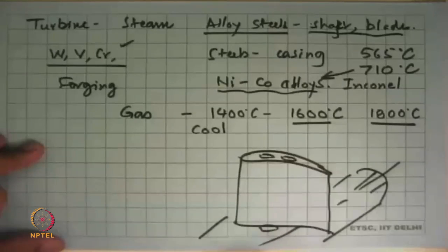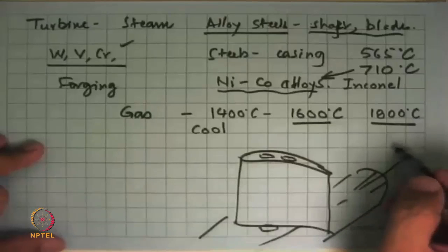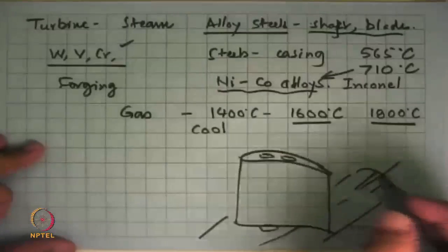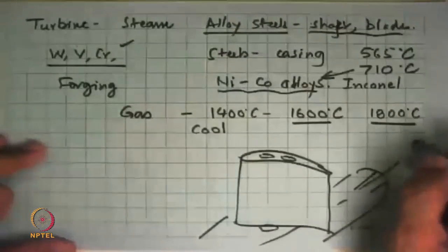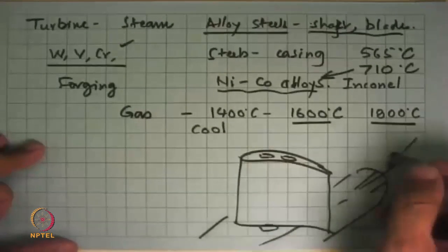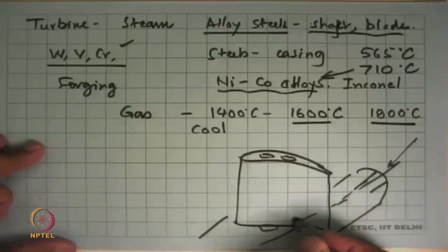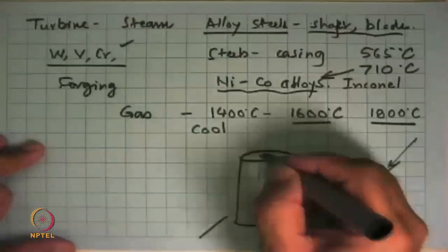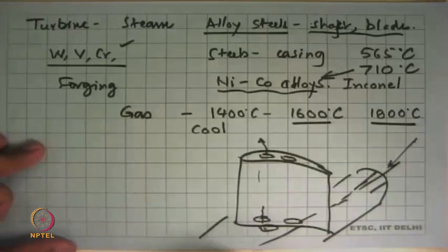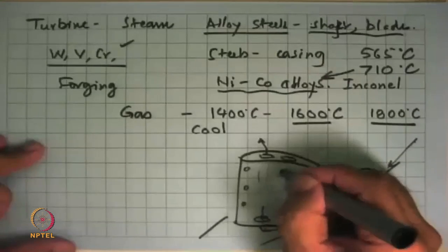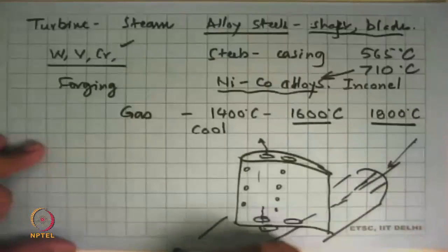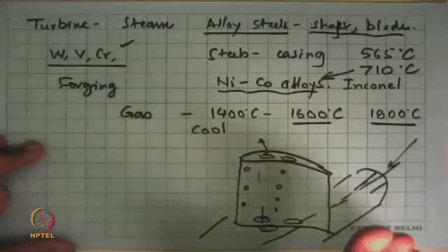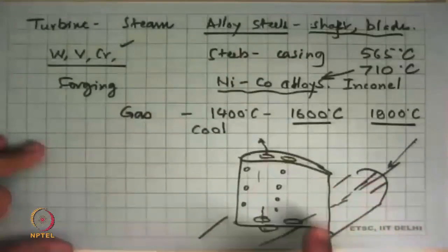This shaft is also hollow, and some of the air from the compressor, say about 700 Kelvin, 800 Kelvin, 900 Kelvin temperature, instead of going to the combustor, bypasses that, is pumped through the passage in the shaft, comes in, connects with openings inside the blade, moves through hollow passages inside the blades, comes out either from the top, or there are small holes on the surface of the blade from which this air comes out, and what it does is that this air goes over this, and right next to the surface forms a small blanket of cool air.